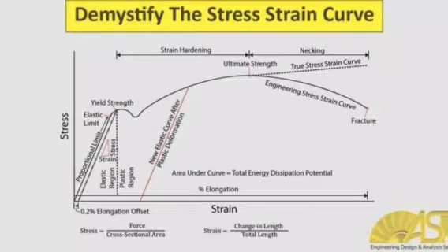This is the stress and strain diagram. It shows how the material behaves in a certain way. In the elastic region, if pressure is applied before it reaches its proportional limit, the material will return to its original shape. Once the material reaches yielding stress, or goes past the proportional limit, the material will begin permanently deforming. This is commonly called plastic deformation. At this point, the object will continue to elongate with a constant load.